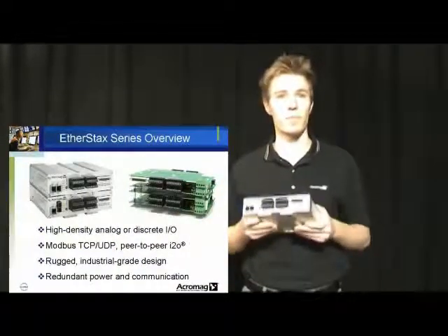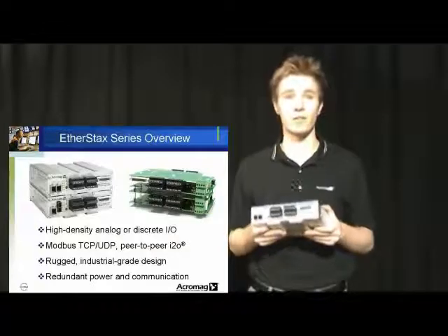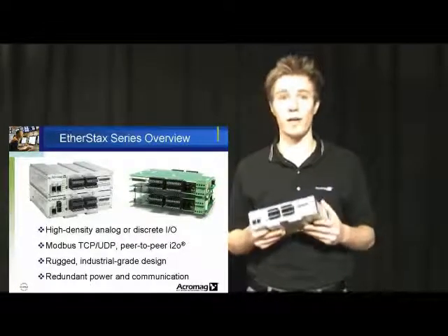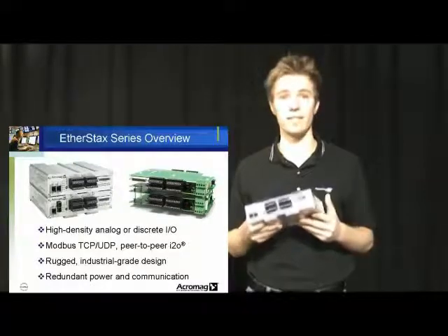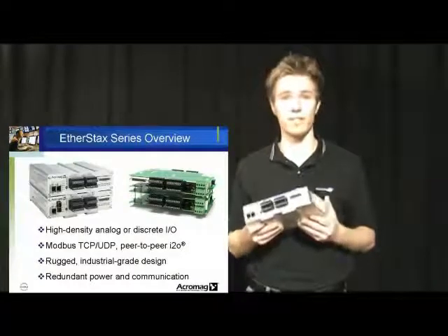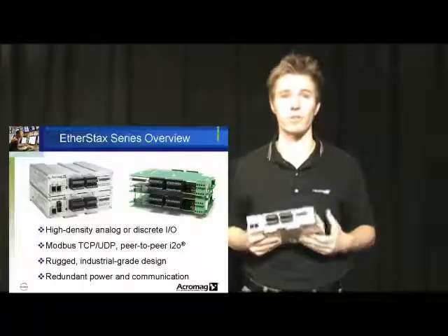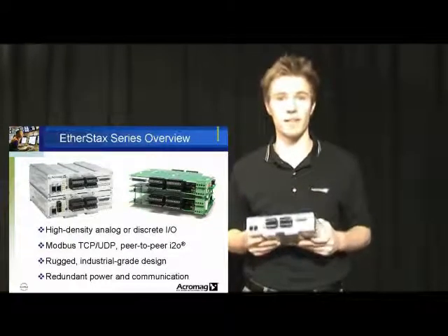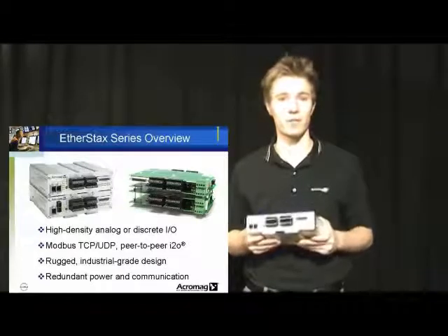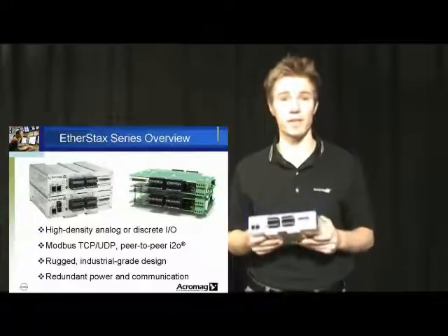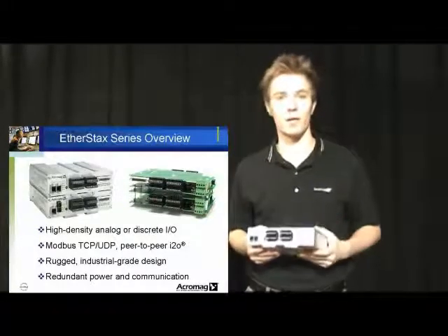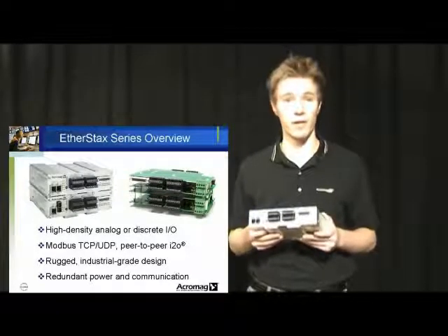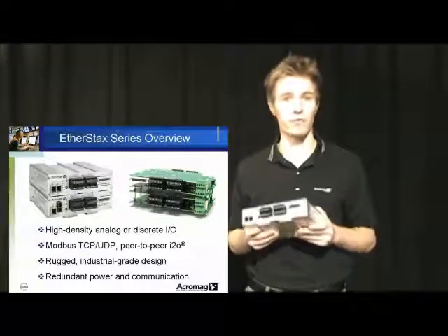The EtherStax are made to interface any analog or discrete sensor signal with Modbus TCP/IP or UDP/IP protocol to provide for easy and efficient integration with your facility's existing network infrastructure. These modules are made for high-resolution, fast scanning with 16-bit signal conversion that can handle scanning and update rates up to 1 kHz. Each analog input also has its own non-volatile integrator totalizer register, which is perfect for flow applications